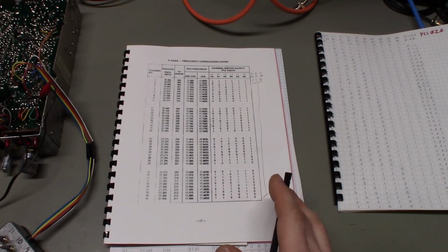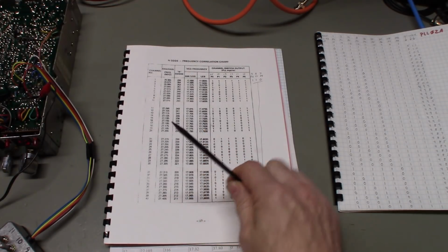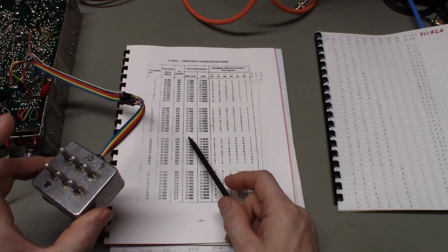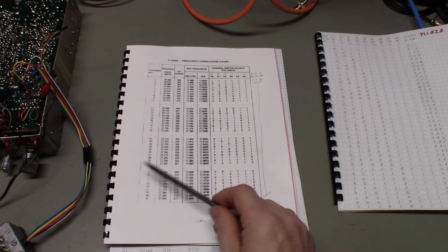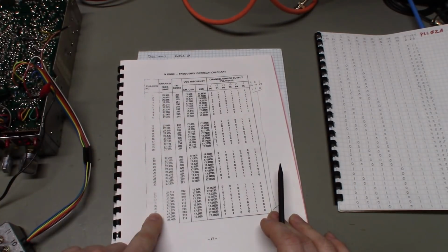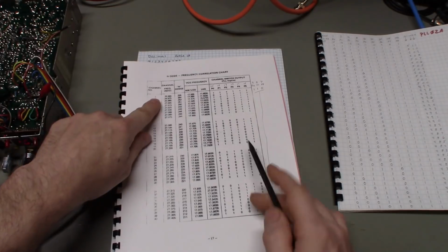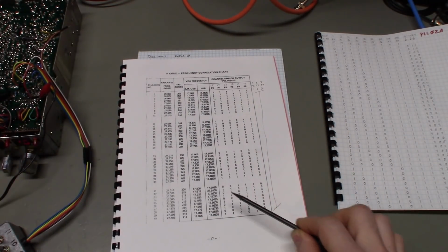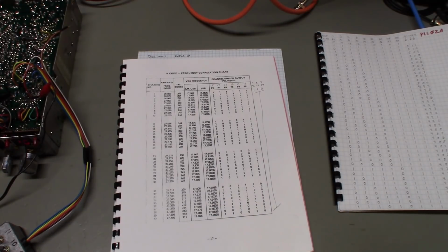The radios become unusable on sideband because they're unstable. You can do what I've got hooked up here. Just using toggle switches, you can get extra channels, because you can change the frequency. Remember, when you turn the channel selector down here, you're just changing the binary programming to the PLL, and that's nothing but a ground and a voltage source.